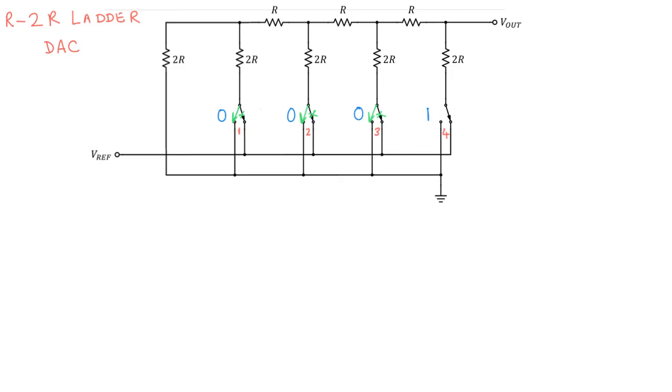So if you look at the output of the circuit, the way to do it would be to start to analyze this circuit from the left hand side. So this 2R and this 2R are in parallel to each other. So the combination of this circuit would be simply a resistance of value R connected to the ground, and that goes and connects at this point, right?